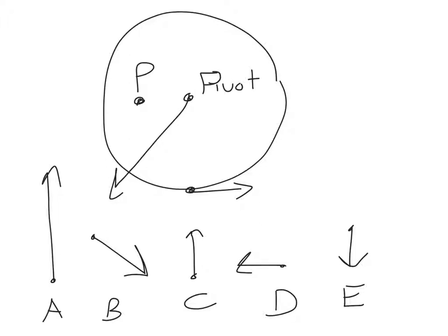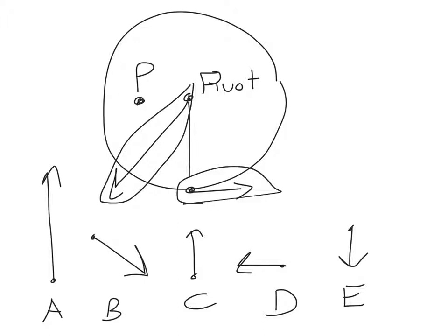Well, let's look at the current torque on this system and see what we've got going on. I'm going to look right away at this force. This force is big. It's twice the force size of the other force there. But it's acting on the pivot point. So there's no torque coming off of this force. So we don't need to cancel that one out. So basically the only torque we have to cancel out would come from this force right here. And if we look, it's about half the size of that big force, and it's acting at 1 full radius.